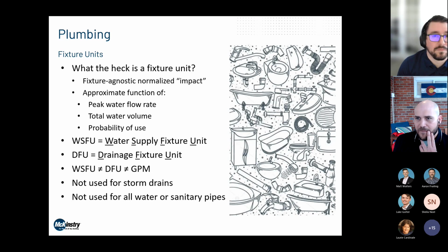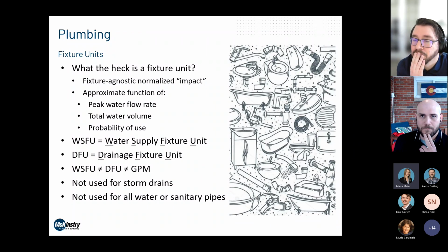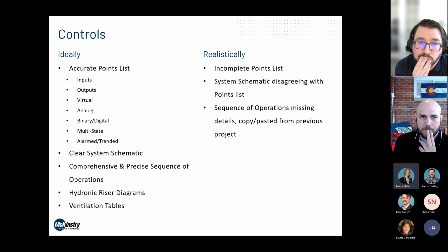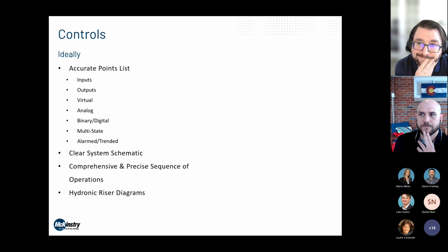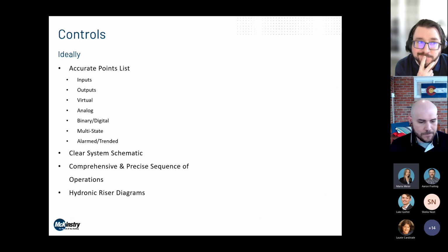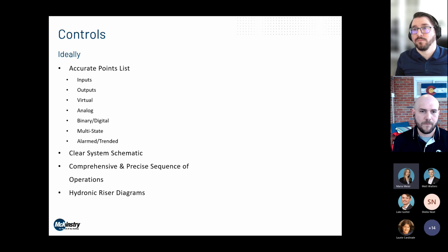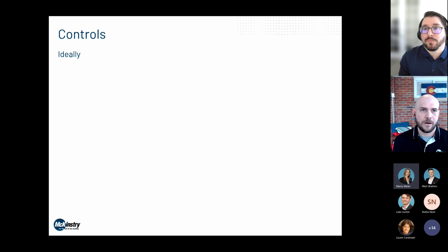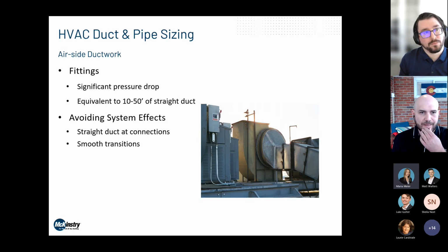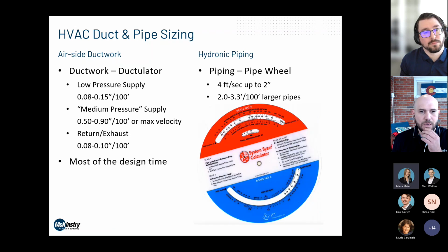Somebody's got a hand up. Yeah, that's me. Quick question, and it's a couple slides back. Something that is actually in the design guidelines for the district is oversizing the chilled water system by about 30%, which is probably a little bit more than the norm. But they don't have any redundancy, right? They don't have any redundant systems that can back up if one of the chillers or both chillers go down.